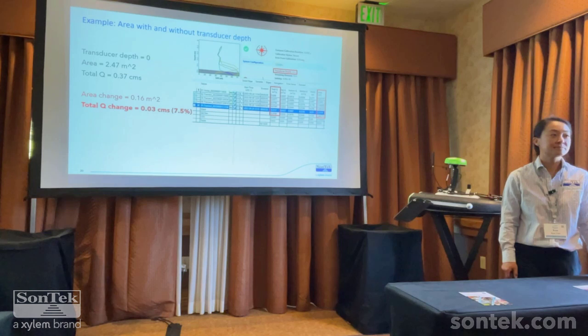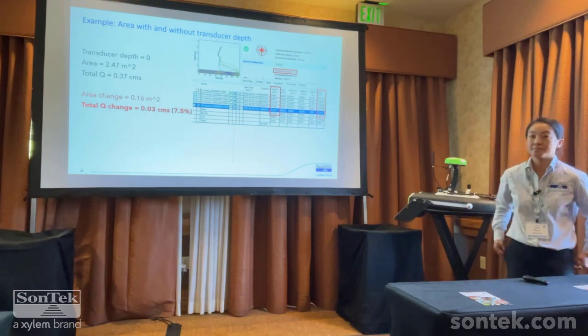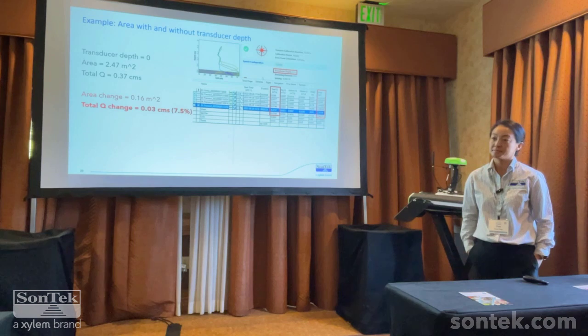And your exposure time can be less. We say you have to move smoothly across, but you can still get a decent discharge measurement if you're moving across and then a tree's coming down and you move back towards the bank you started on, and then you continue on once the debris has passed. You can still get a decent measurement that way, depending on conditions.